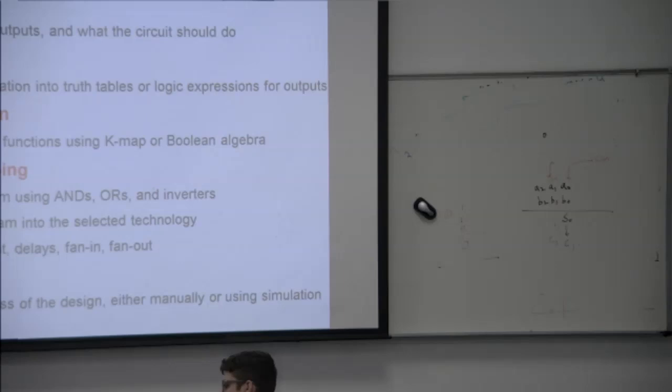So how can we implement logic minimization? We can use different techniques: algebraic manipulation, or K-map. Both give us reduced expressions, but they simplify each individual expression individually, not collectively. So collectively we do logic sharing. Then we do technology mapping. Should we implement in AND OR logic? Should we implement in OR AND logic? Should we implement in NAND, or in NOR? This is called technology mapping.